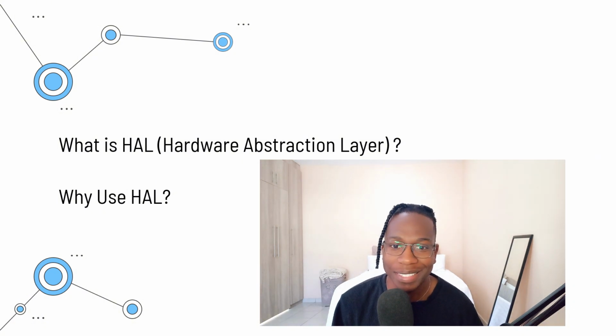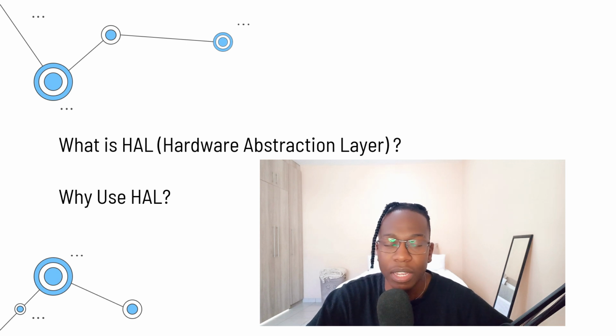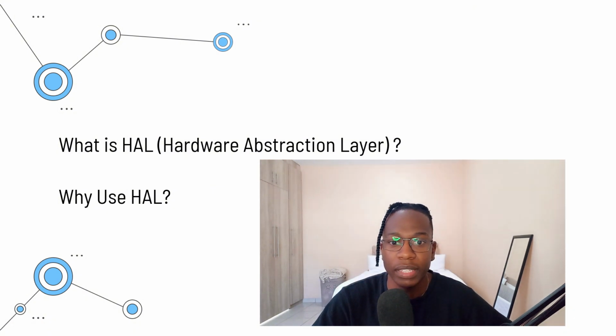HAL abstracts the complex low-level details of the microcontroller. This essentially makes it easier for you to develop applications. So instead of writing code to manipulate specific registers within the microcontroller itself, you can just use HAL functions that are more intuitive and easier to understand. This basically allows you to focus more on the application logic rather than the hardware specifics and the general architecture of the microcontroller itself.